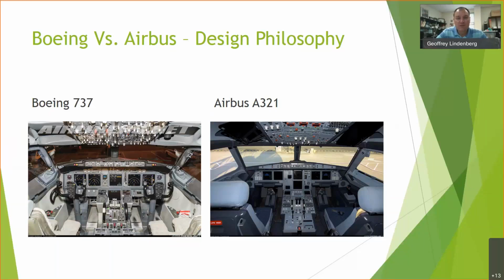versus a Boeing, for instance, is that if a Boeing pilot pulls back on the column to bring the nose of the airplane up, the airplane will continue to go up and up and up until it stalls, with little protection. They rely on the flight crew to understand or know the limitations of the aircraft more. The Airbus A319, 320, 321 family, however, has flight control envelopes, so if the flight crew grabs, and I remember I said they have a side stick,